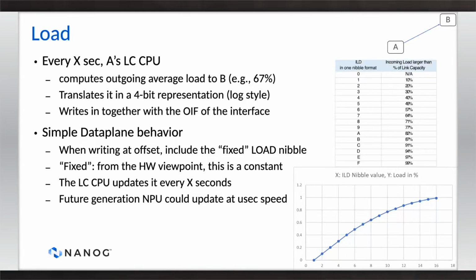And I know most of you think, what can I do with 4 bits, right? I get a measly 16 values. We implement this logarithmically. So we're going to add emphasis on the higher values, right? We're looking at things in the 80s and 90% to have smaller intervals between the buckets, whereas if your load is between 10 and 15%, we really don't care.